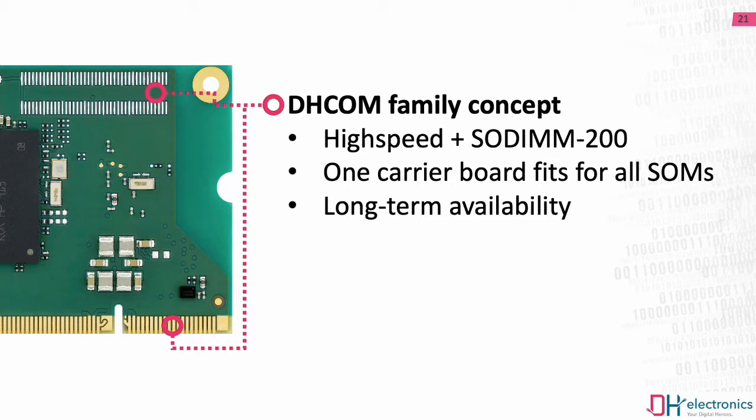But besides this, the family design is also very helpful when it comes to long-term availability. Like maybe in 15 years from now, STMicroelectronics might decide to discontinue the MP1. But maybe your baseboard is still doing its job fine as it should, and therefore you try to avoid a huge redesign, right? In such a situation, you can really rely on the family design, because even though the SoC itself might be discontinued someday, it is still very likely that we are having a new revision of the DHCOM module with maybe an STM32MP2 or MP3, who knows, or maybe even newer. And it is still compatible to the family design, and therefore you can really extend the lifetime of your existing baseboard by simply changing the DHCOM module to a new revision.